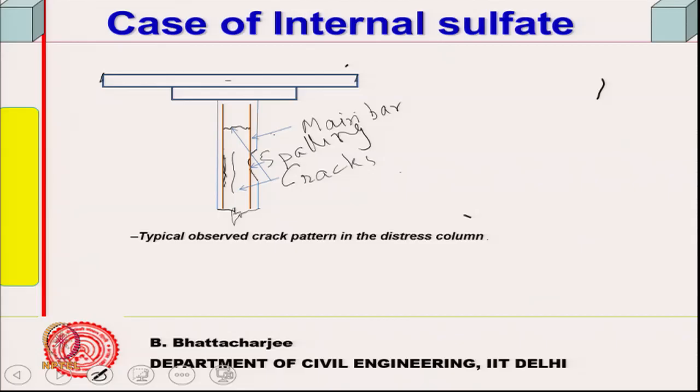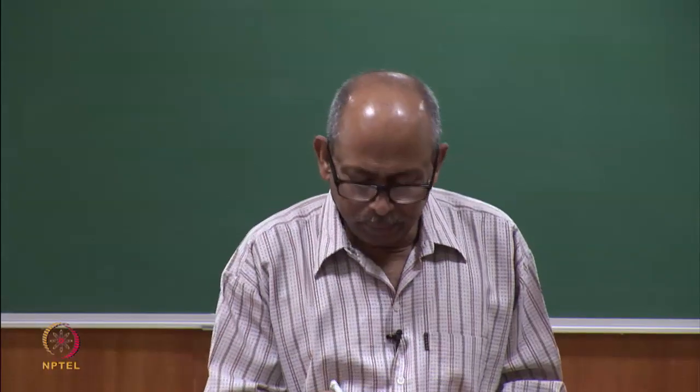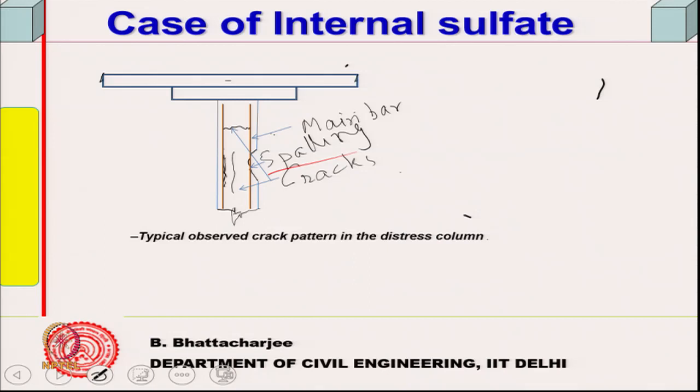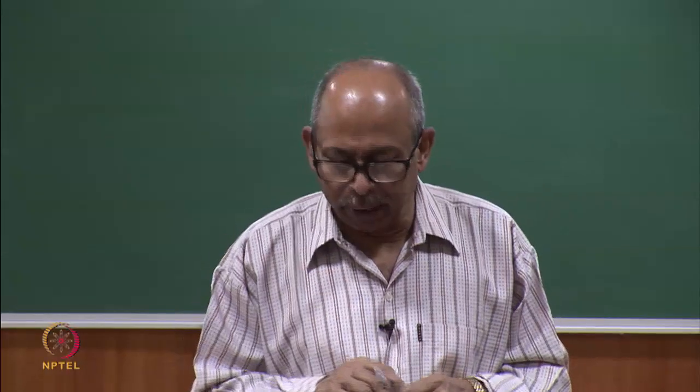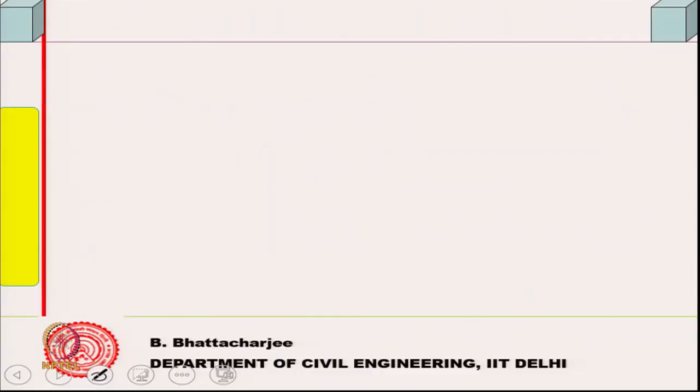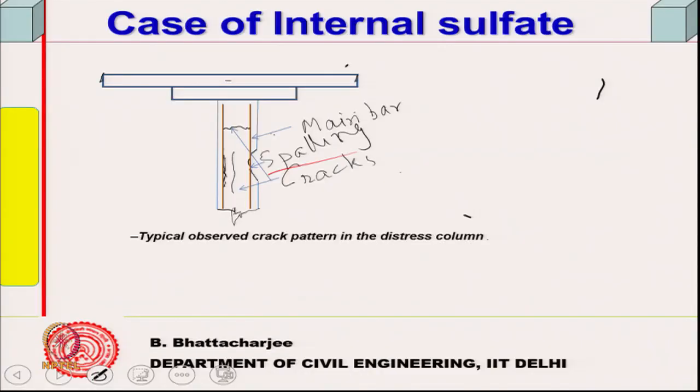Now, this is an example of an internal case that I came across, 8 months old concrete, with cracks in the vertical direction inside, flat slab construction. A chunk of the concrete even came out from the center of the column, spalling has occurred, particularly in the corner, I mean at the center height in the corner. This is, I suppose there is another diagram, or if not I will see, something like this. The corners have come out, exposing the rebar, somewhere like this it is exposed, and at the center of the bar.